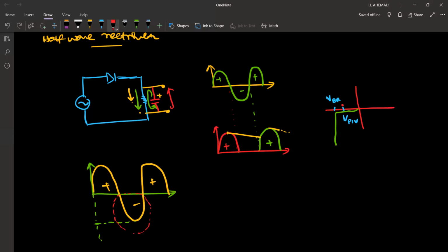As soon as the voltage we apply exceeds peak inverse voltage, the diode doesn't get damaged immediately, but there is a chance of damaging the diode if we use it above peak inverse voltage. Is the difference between breakdown voltage and peak inverse voltage clear? Do you get the idea of breakdown voltage and peak inverse voltage?